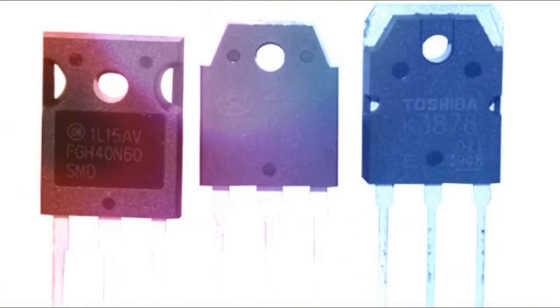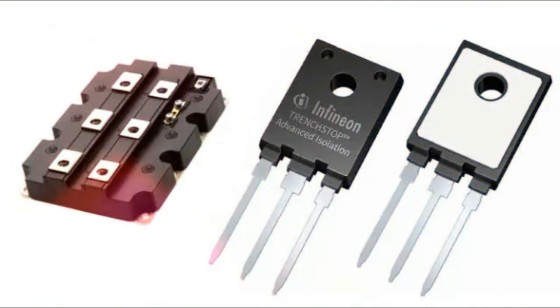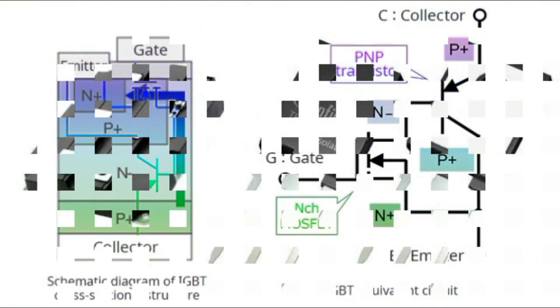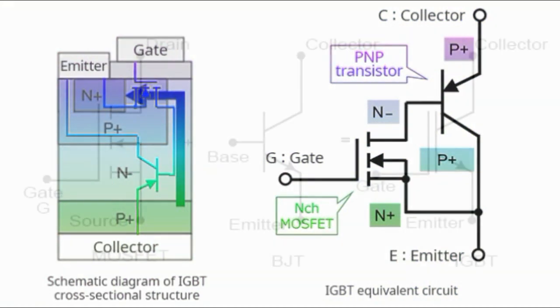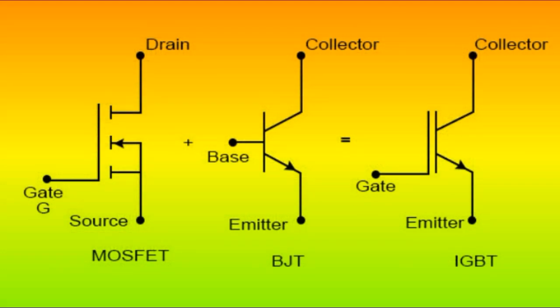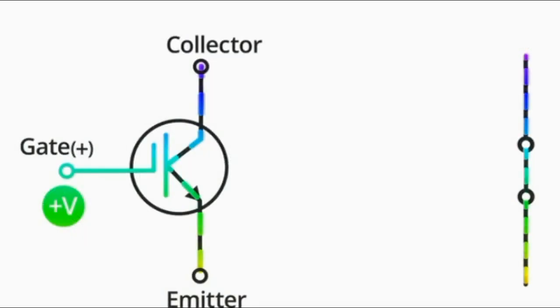As the name suggests, the IGBT is equipped with isolated gate MOSFET technology and also has a common bipolar transistor. The result of such a combination has the output switching and conduction characteristics of a bipolar transistor, but is a voltage-controlled device like the MOSFET.